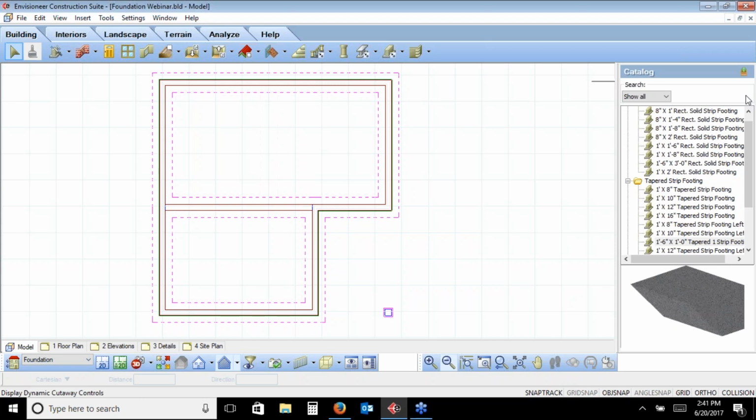I'm going to turn off the visibility. I'm just going to click on this view filter right here that allows me to come up to elements on terrain and turn off the visibility of the grass so we can see just the walls and our foundation. I'll click OK and they'll disappear. So my footing is still at the same height. I need to get rid of it, so I'm just going to delete the footing itself so we can see the stepping foundation.